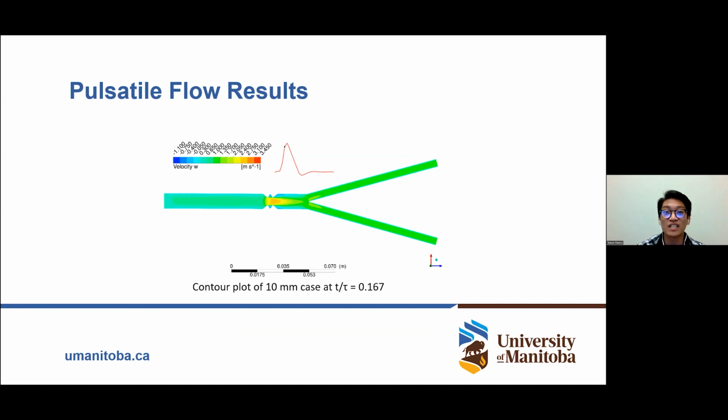At the bifurcation, a faster velocity is observed on the inner portions, which may be explained by jet structures created by the foreshortened section, which concentrates the flow directly to the bifurcation.